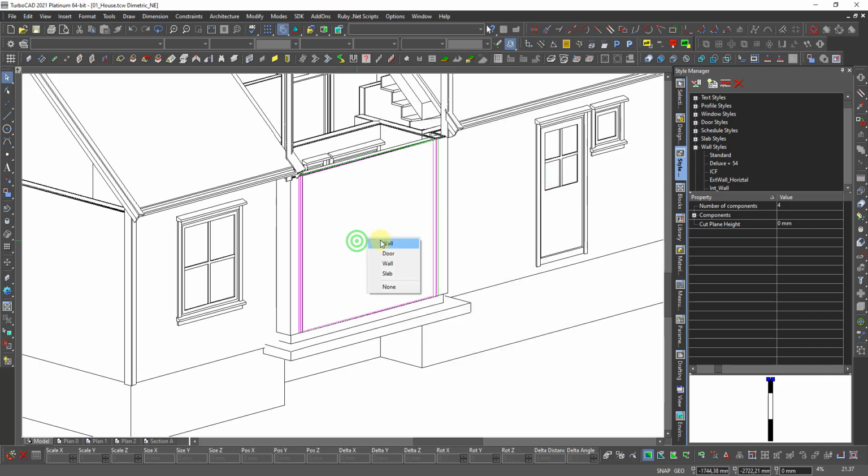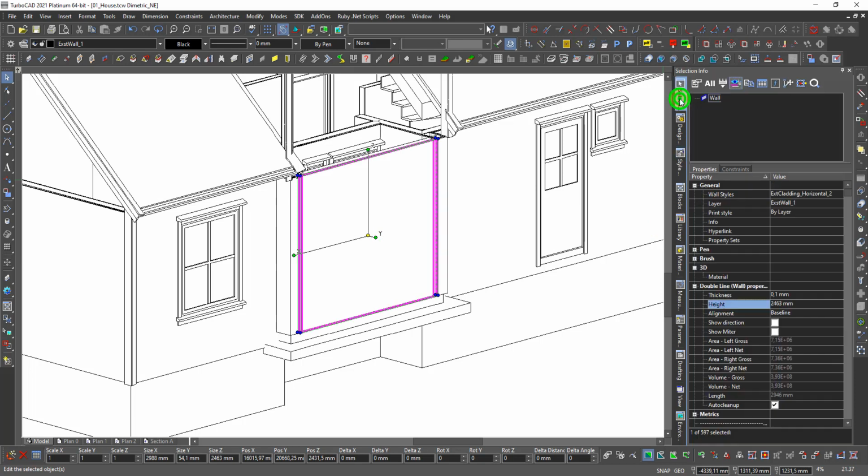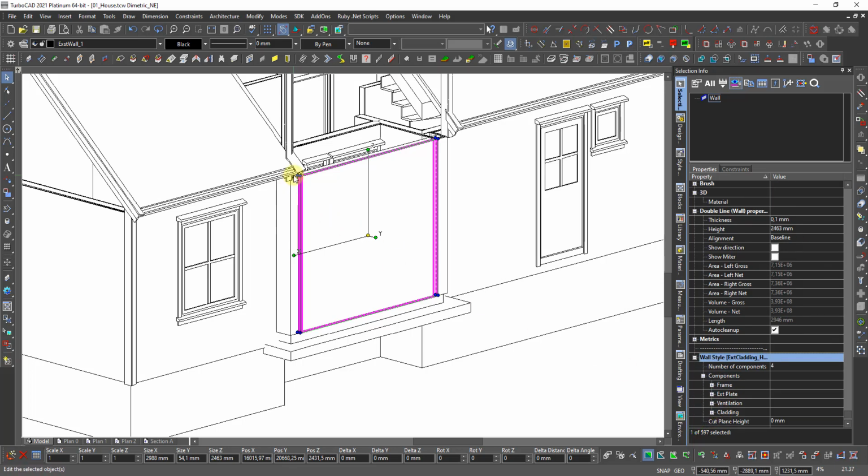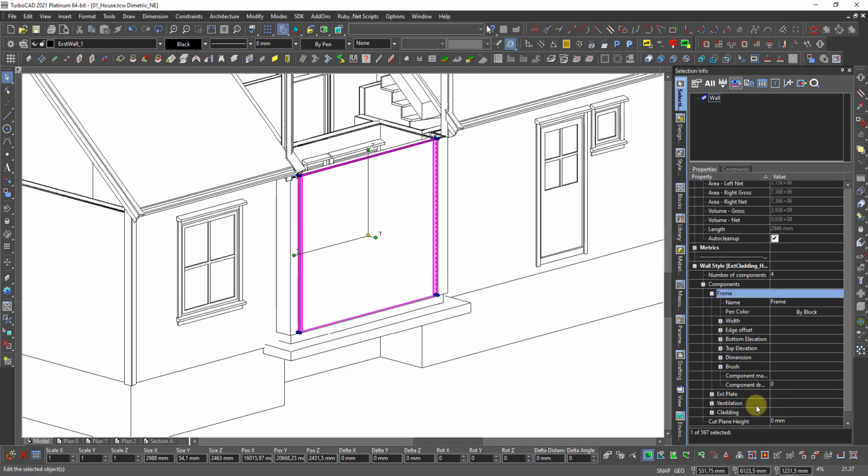And then I take this wall, and that should be the new style. Not this one, but this one. Then I go to the style and I lift up everything, because now it is the same height. I have to do it on every component, and then you have the bottom elevation. From wall bottom, Control V, enter.